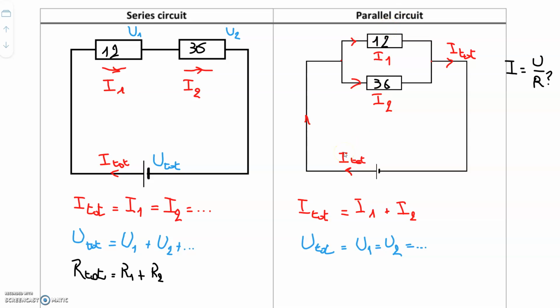In a parallel circuit, you would not be placing those tubes behind each other, but next to each other. You would create several holes in your vats to sort of connect them through. And something weird happens. Even if you take one big tube and you connect them, as soon as you add another one, even a smaller one, more water will be able to flow from one vat to the other. Something odd happens in this case. The more of these branches you create, the lower your total resistance will become. Because, if we use our water analogy, you'll just have more and more tubes for the water to pass through.